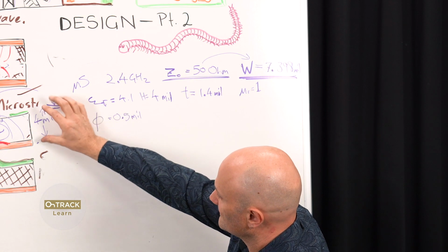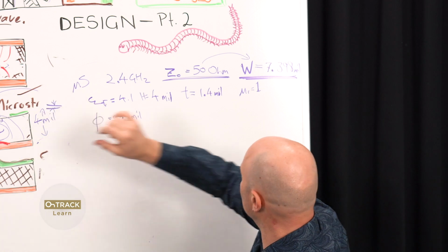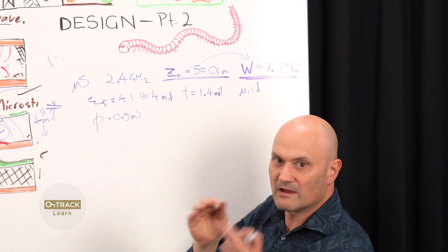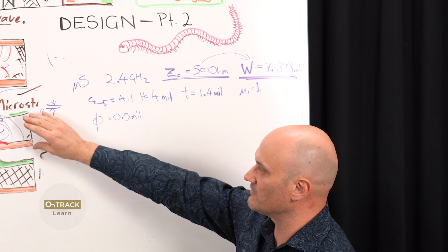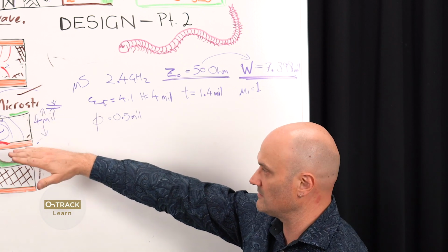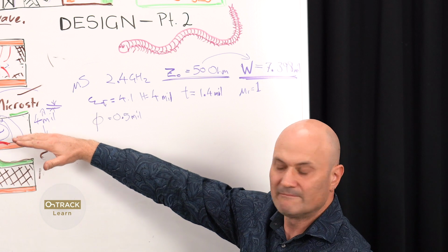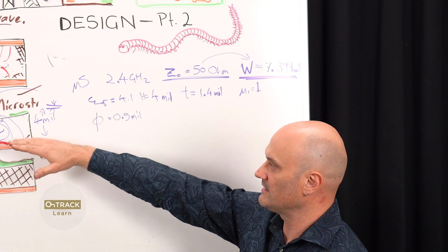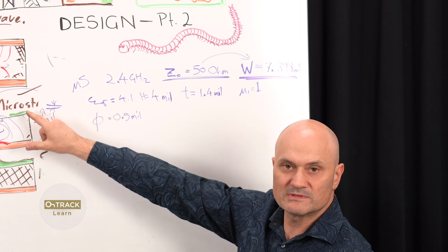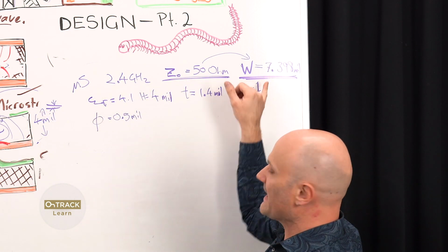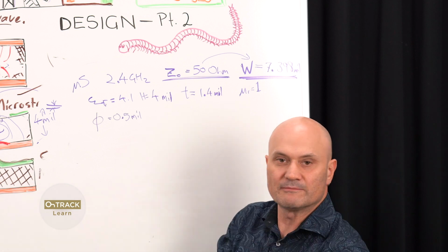And if this height is increased, to maintain 50 ohms, the trace will have to get wider and wider. So this is another good reason to at least have a 4-layer PCB with a reference plane on layers 2 and 3, so that you can have good impedance controlled microstrips without having to have excessively wide traces and take up too much space.